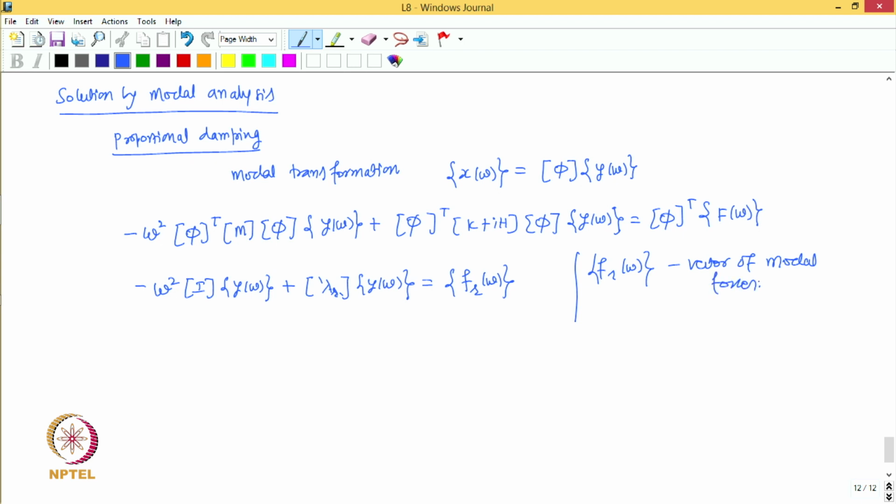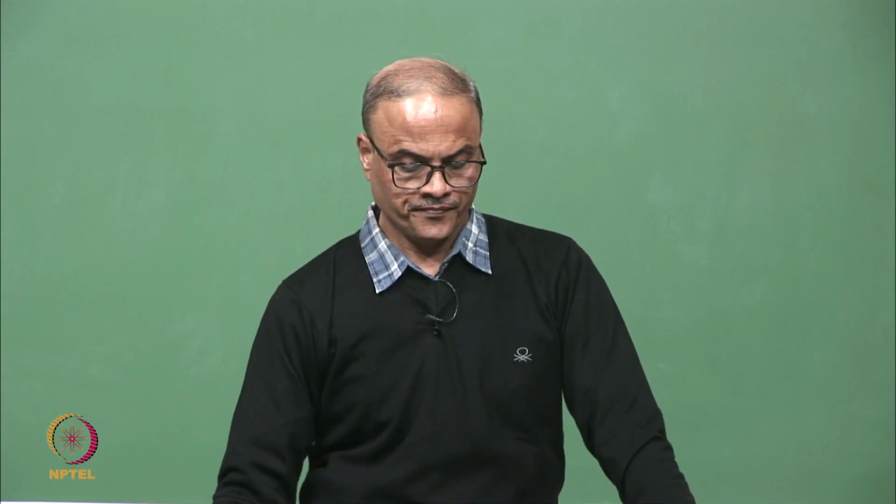So, now as we saw in case of undamped systems in the previous lecture, this again is an equation which is decoupled. These are decoupled sets of equations, while the equations we wrote in the frequency domain using the k, h and m matrix were coupled equations.